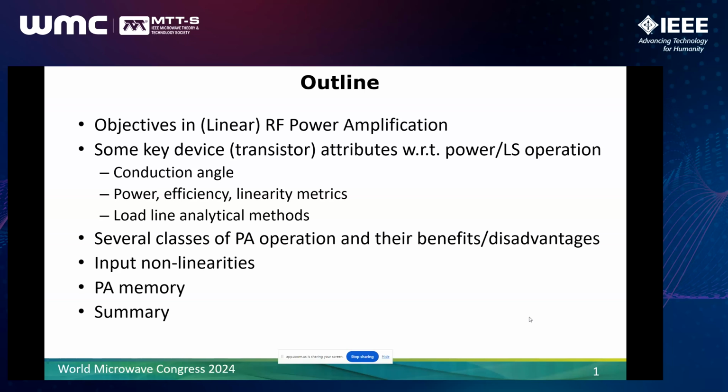We'll look at some key device attributes of the transistor and how those attributes match up and play in large signal power operation, specifically looking at conduction angle, some of the metrics like power efficiency, linearity metrics, and some discussion on load line analytical methods.